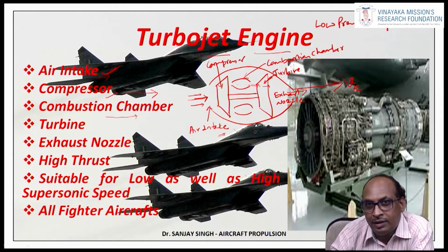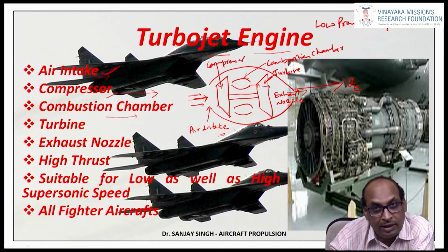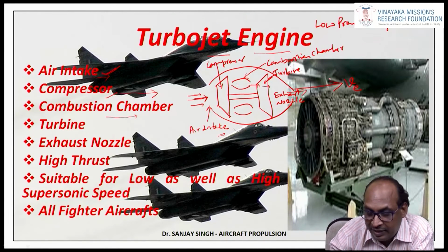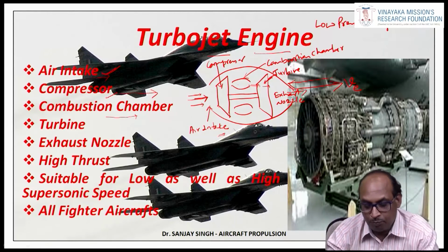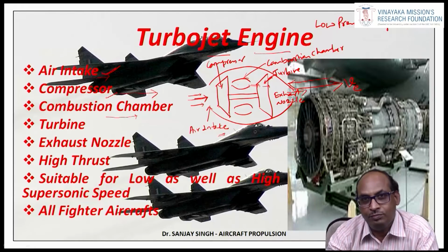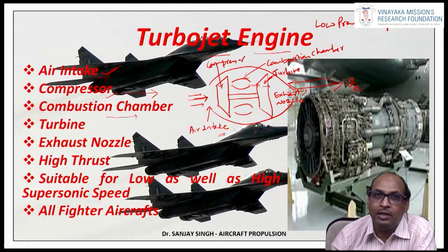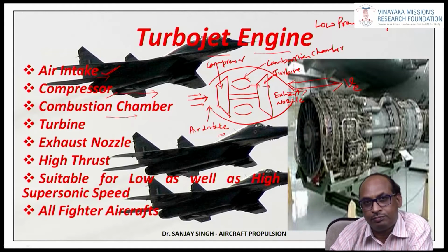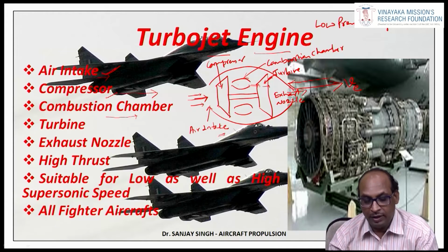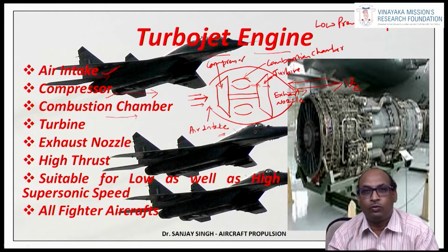So when the gases leave the engine at high velocity, VE, then as per Newton's third law, it will create a reactive force on the engine structure with the same force, and thereby this complete engine structure, which is attached to the aircraft, will make the complete body of the aircraft move forward. This is called thrust force, and in this way thrust force is generated in a jet engine.